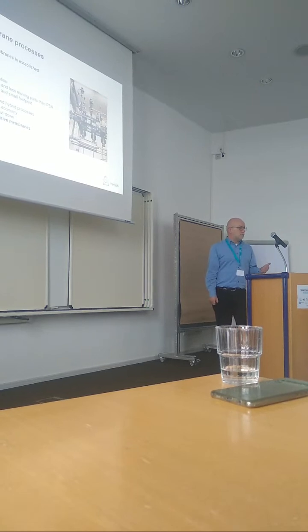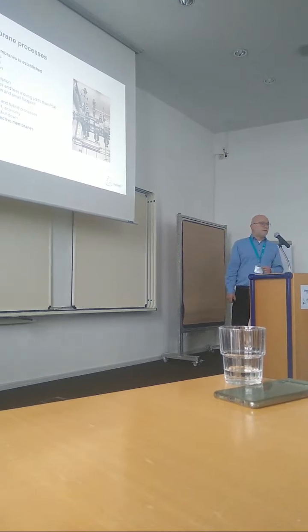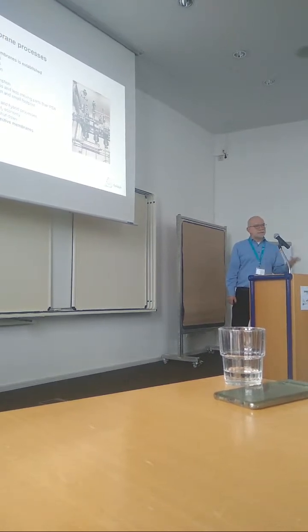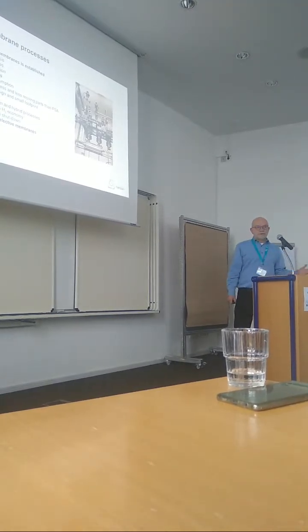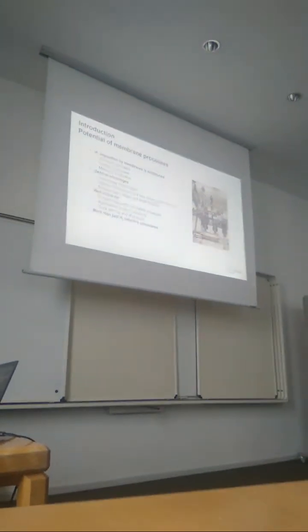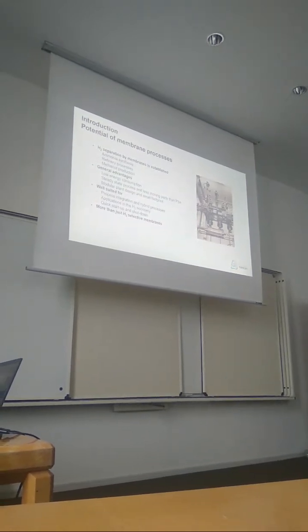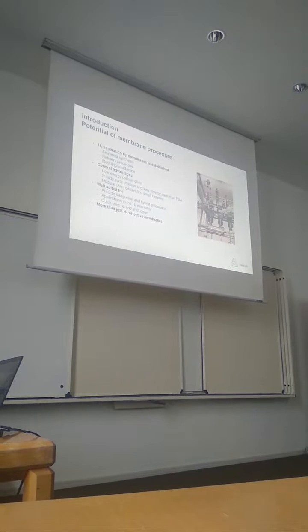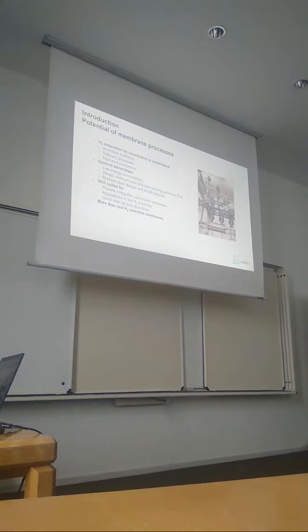That's ammonia, Haber-Bosch processes, that's refinery processes, so anything with catalytic crackers and so on, wherever you have hydrogen in there, hydrotreaters, you've got large gas streams containing hydrogen. You would like to reuse the hydrogen within these refineries, for instance, or big chemical plants, and there you use membranes to recycle the hydrogen. And the same goes for methanol.